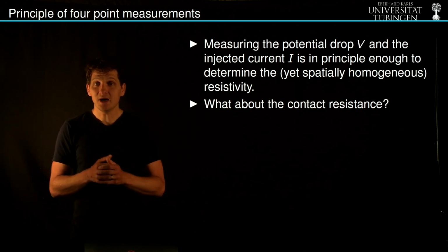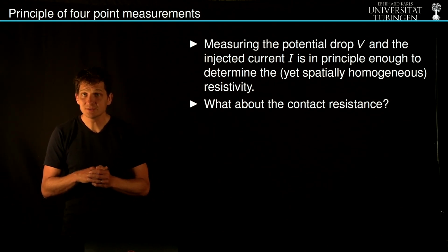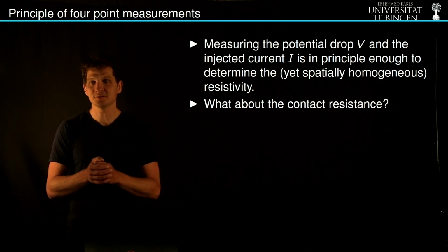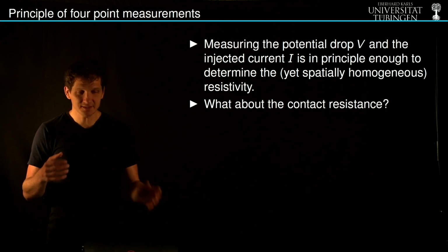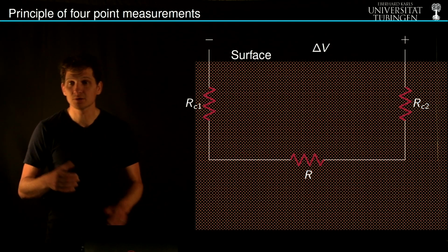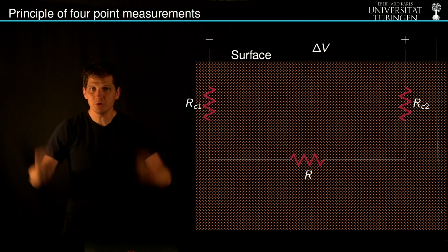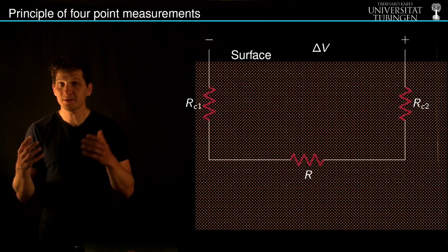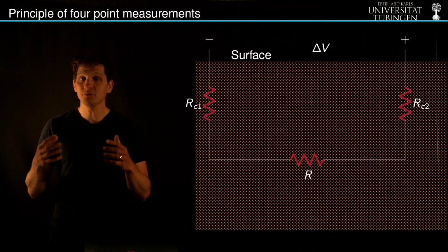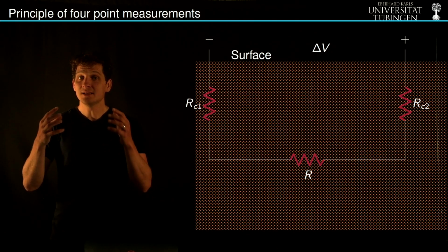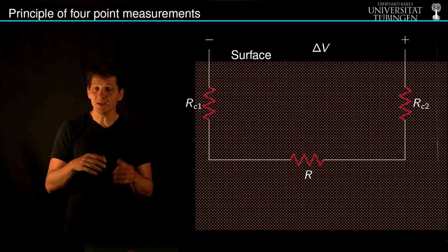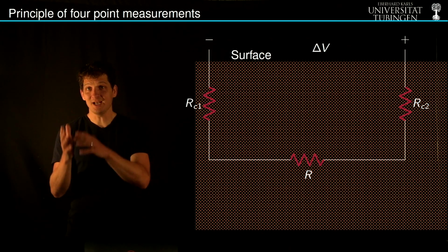However, there are a number of complications, one of them being the way that the electrodes couple with the subsurface. You have to imagine that the electrodes are mostly some sort of metal sticks that we simply push into the surface, and at the contact areas between the metallic electrodes and the surrounding soils, the mechanism of conduction must change from ionic to metallic. Actually, I mean from metallic to ionic.